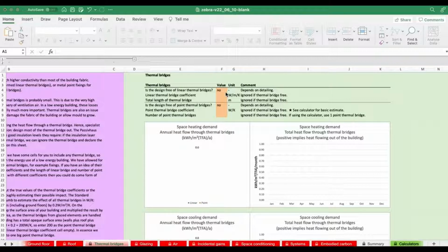And when we're looking at low energy design in much of the world, that's actually what we're trying to do. We're not trying to specify accurately the number of thermal bridges. We're actually trying to design a building without thermal bridges. So you can just answer that question with a yes if you had one of these super insulated, well wrapped in fluff like buildings, which we don't have here. So we're not going to say yes to that. We're going to do something else.